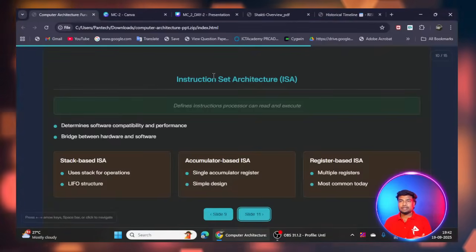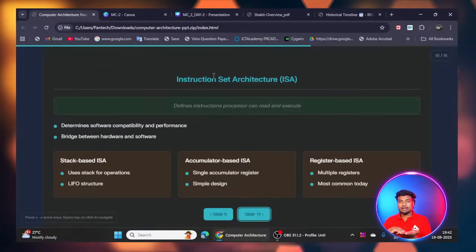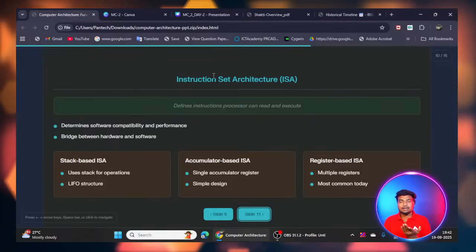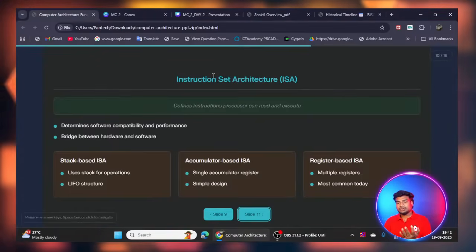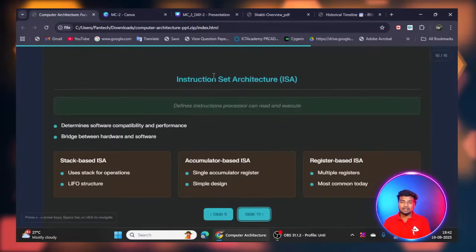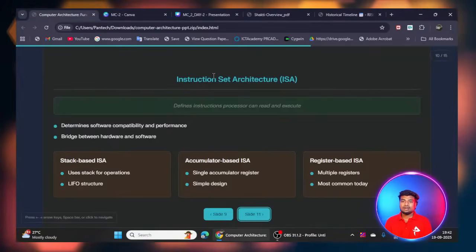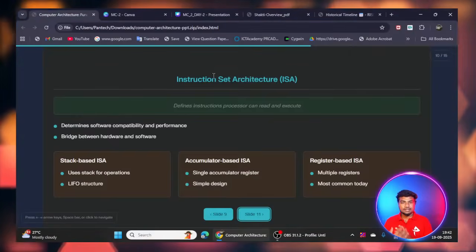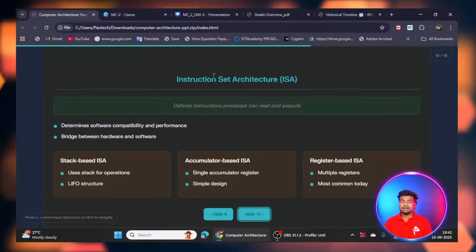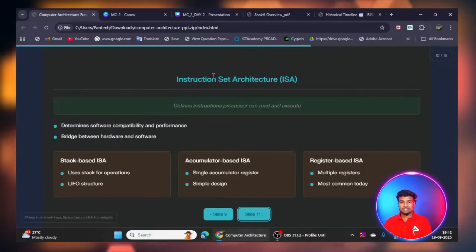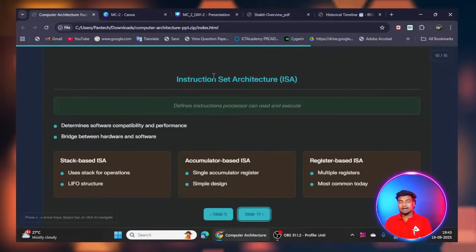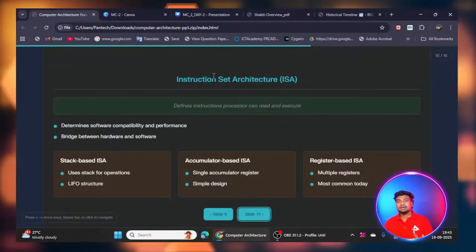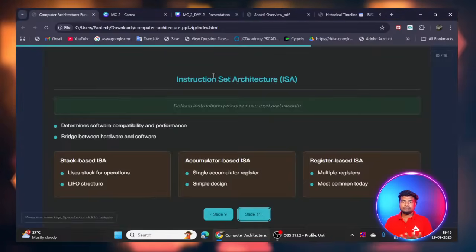If you see the register at the upper level, the base of the register is a D flip-flop only. So we are going to write the RTL code or design code for the registers, the buses, and then the architecture. We have to write the Verilog code for this architecture. This is the main work of a design engineer. By using this architecture, we write the RTL code, and based on the RTL code we convert into gates, then into transistors, and we build the chip. So this is the basic flow.